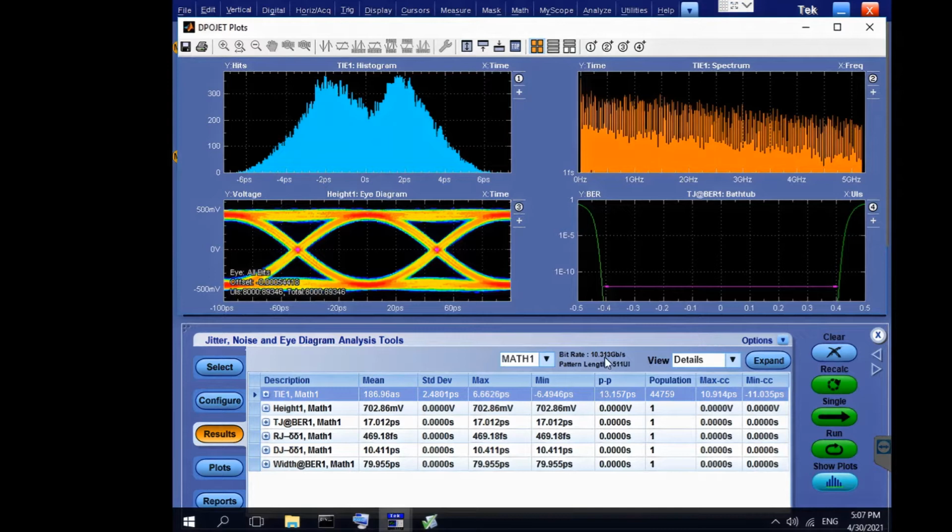It will put in place a software clock data recovery and detect the data rate, which is the correct one here. It will also detect the pattern length of the PRBS. I'm not totally conformant to the standard here because I'm using a 511 UI pattern, which is a PRBS9, I guess, as I didn't have the PRBS11 requested by the standard.